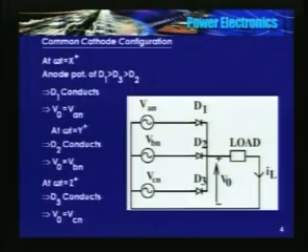And when the diode is off, the anode potential is its phase voltage, whereas cathode potential depends on the conducting diode, because for some time the cathode potential is VBN, and for some time the cathode potential of D1 is VCN.